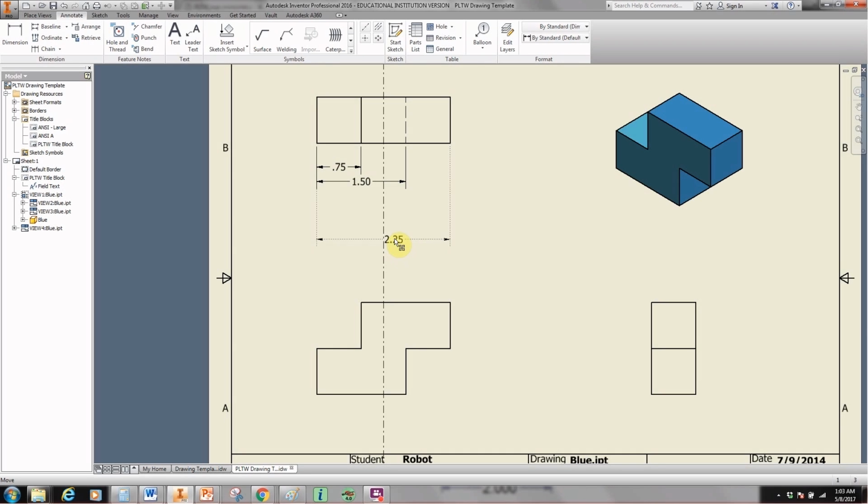So that line right there, that dash, dot, dash line, is showing me I'm off center. And as soon as I center it up, it becomes dotted. So save yourself the trouble, save yourself the grief, save yourself from having to hear me tell you you didn't do it correctly, and just grab the dimension line. Grab the dimension line and move that, and that 2.25 will stay centered. There we go. We got our dotted lines. It's back where it belongs.